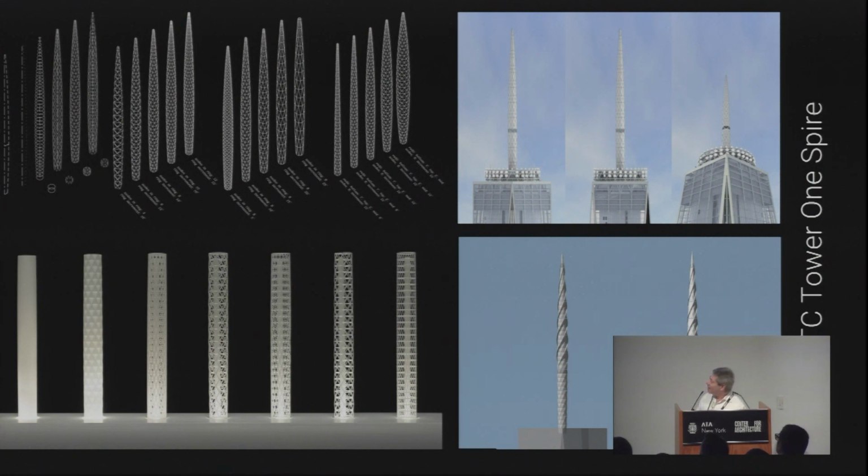We began work on the project in late 2001, and we were still using our system, which was called AES. And not long after that, we started using AutoCAD. So much of the scripting that I used to implement all the parameters and the variations in the design of the spire was done with scripting in AutoCAD. Initially, it was a lattice-type system, like you see on the lower left. We were also studying lighting, in addition to so many other aspects. Eventually, we decided to use a panelized system, mostly for structural reasons.